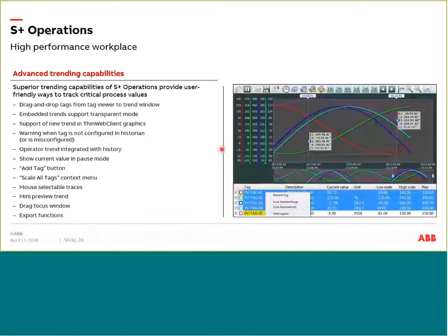The other cool feature that we have is our powerful trending software. Within S+ operations, we have a trend database. So here, if I have a trend open and I have a graphic open as well, an operator can drag any of the tags or items and drop it on my trend, and it'll trend the entire history of that particular tag.